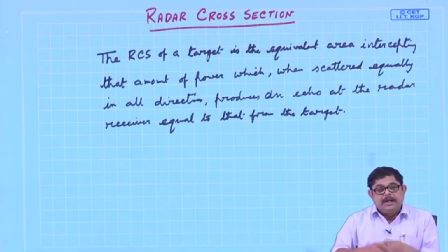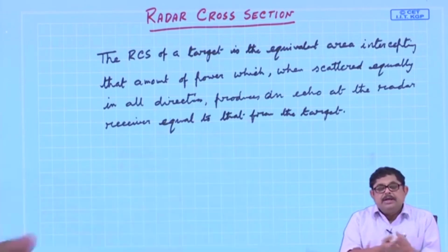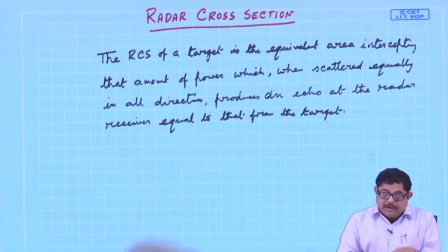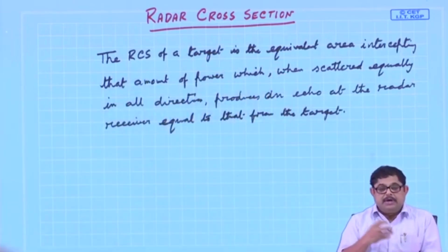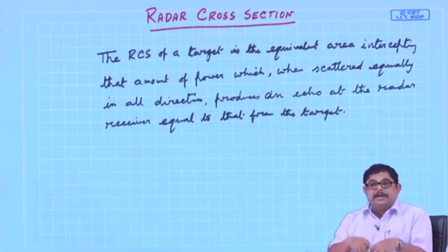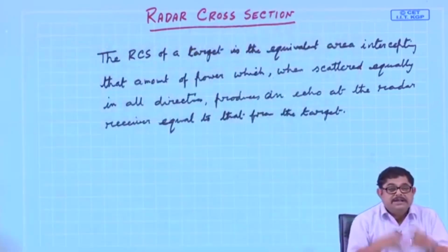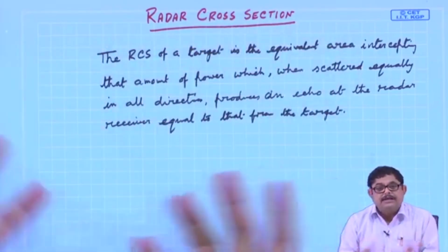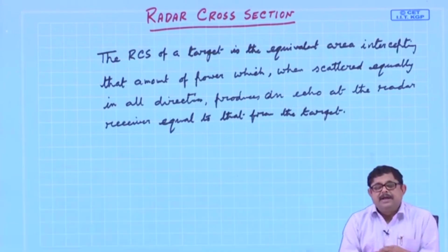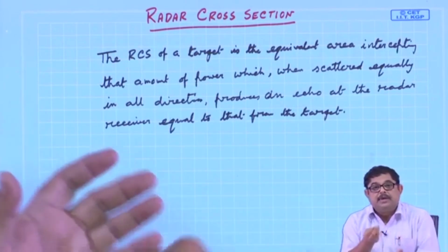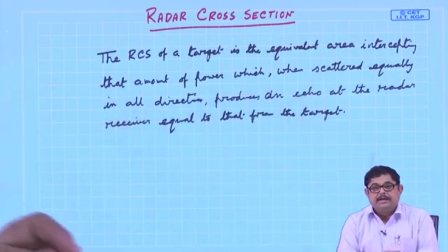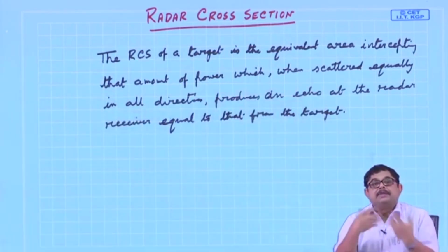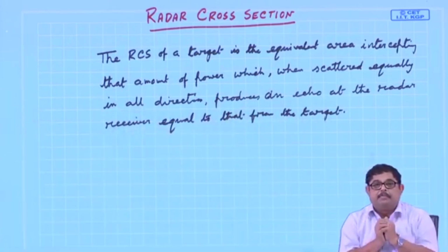We have seen in antenna classes what the equivalent electrical area is. Now, RCS is not only that, because that is the receiving part. While receiving, this effective area comes, because we can calculate the power intensity at a point, and that multiplied by the area is the total power.